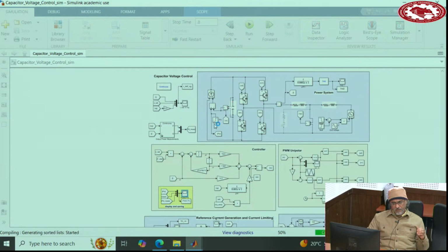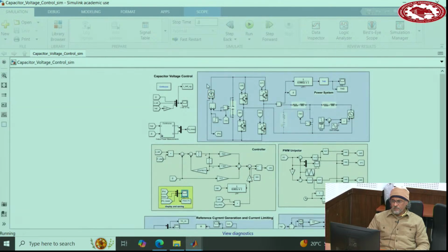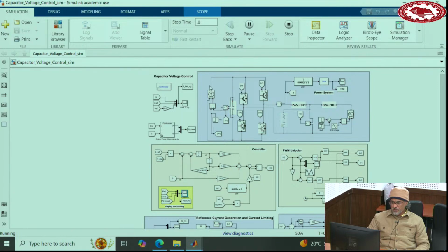That will be the amount of current coming. Whatever power you want to assume coming from the previous stage, put it here, and then divide it by the voltage, and then apply that as the reference to this current source. That will cause this current source to generate the voltage here, to generate the power here.